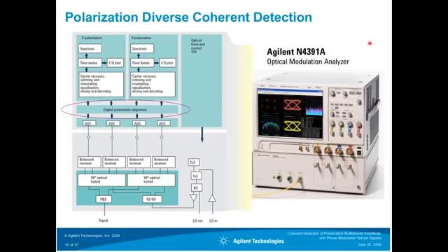But before going to channel matrix estimation, I will briefly show how this looks in the instrument we have just recently introduced. So what we have down here is again the signal, polarization beam splitting, 2 IQ demodulators or 90-degree optical hybrids. We have a tunable laser source that acts as local oscillator, splitting this into 2 parts so that each IQ demodulator has its own local oscillator input.